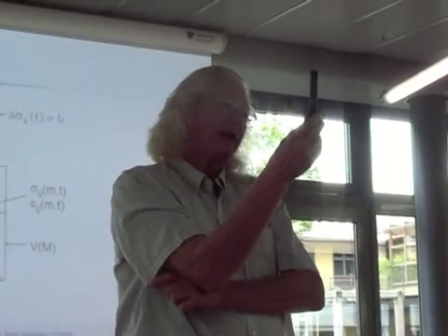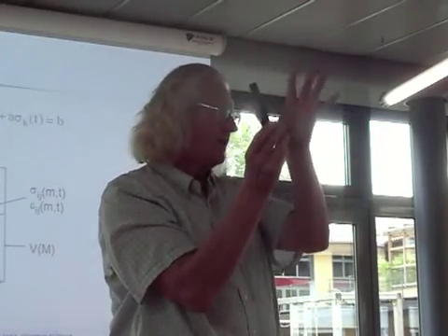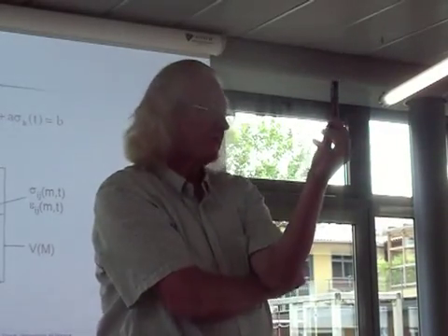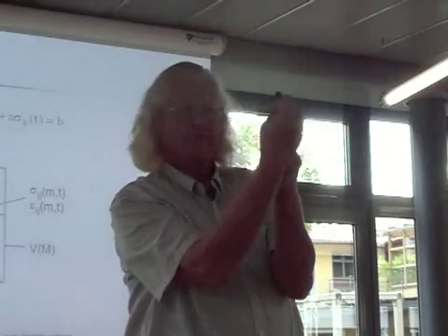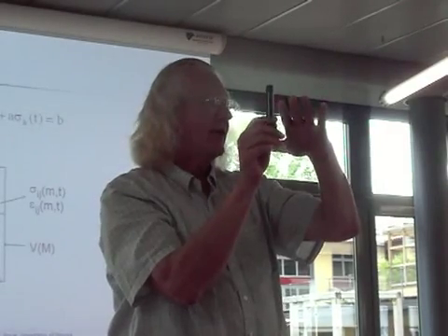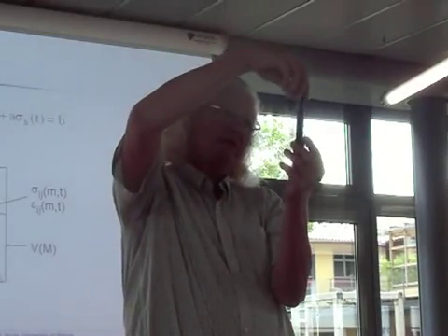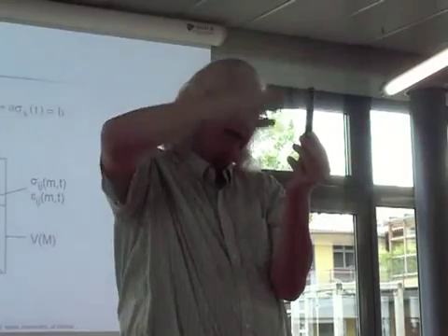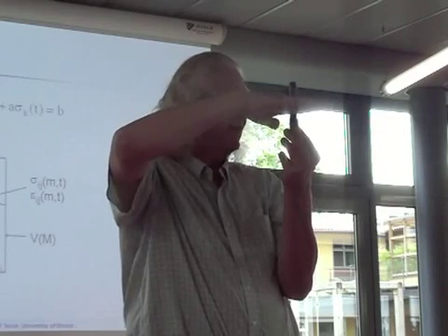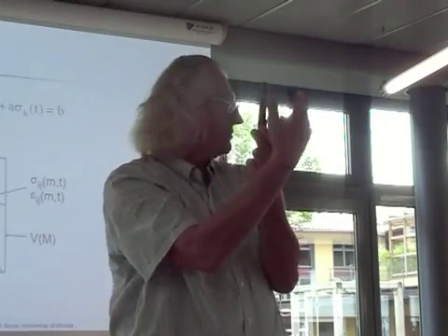But let's think about this now in a little different way. That's just calculating macroscopic stresses, and that's Dang Van's idea of the macro stress. But now think about this bar being filled full of crystals, 1 millimeter cubes. Each of these crystals will have a slightly different orientation, which means the stresses in each crystal will be different. If I load this with my force of 10 acting on this unit area, the average stress in all crystals in this direction is 10, but in each individual crystal the stresses are a little bit different.